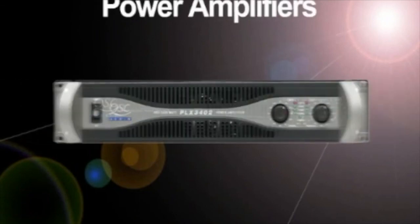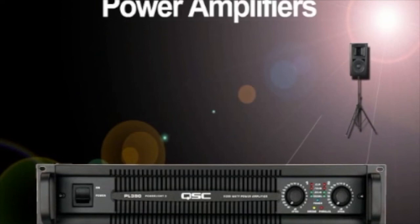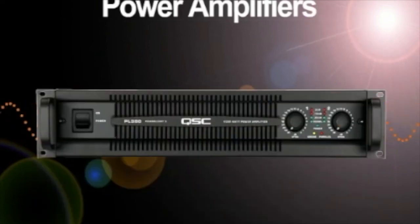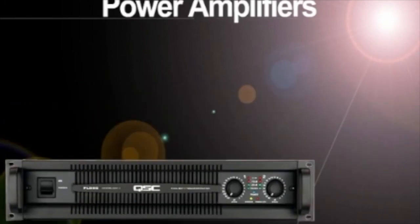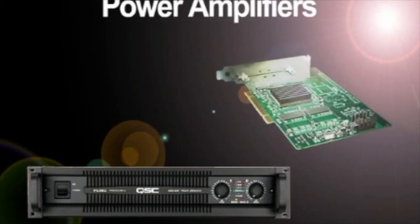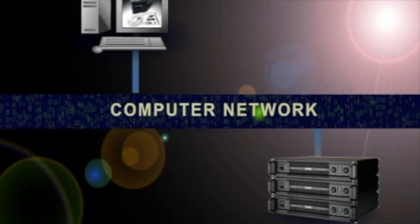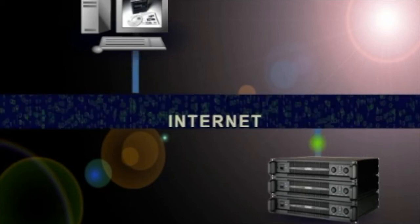Power amplifier technology continues to advance. Today's power amplifiers are capable of detecting shorted loudspeakers or cables and automatically reducing their output to prevent thermal overloading or failure. With advancements in digital signal processing, power amplifiers can now host a DSP card that provides onboard loudspeaker processing. Additionally, power amplifiers can be controlled and monitored over a computer network from a remote location or over the Internet.